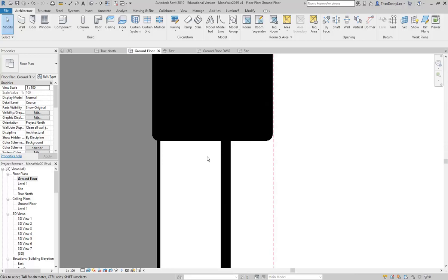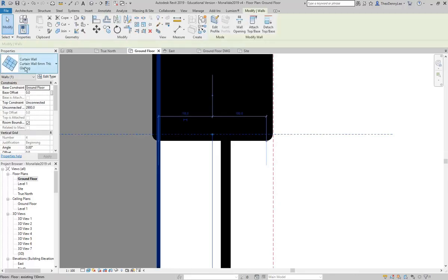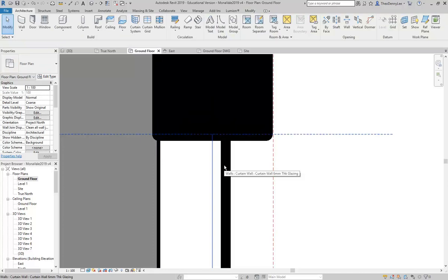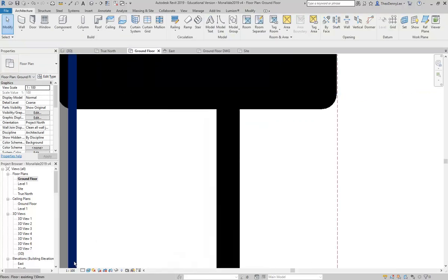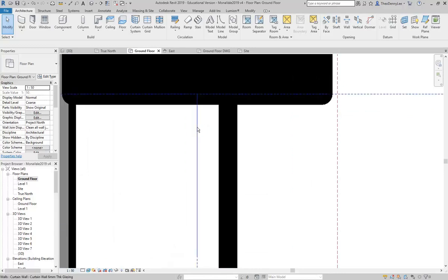the people who made this wall probably even thought it was going to be less, probably thought it was going to be 6 mil, because that's what they've called the wall. You don't usually draw it that thin, just because the line weight that you use, even at 1 to 50, is going to hide that thickness, right? Because the ink in the pens you're using is wider at that scale than 10 mil.